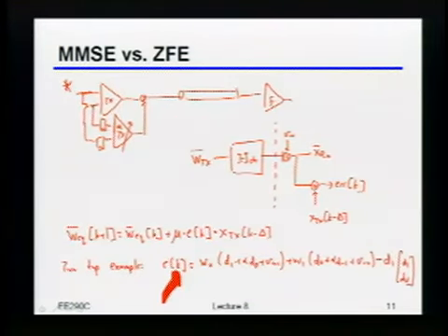That's really the problem. So assume if you have an analog transmit, you have some analog noise, then you are basically doing MMSE just for that. Yeah, okay, so you're right that if the noise was all on the transmit side, then you are doing an MMSE for whatever noise was... Oh, no, actually, I'm sorry. That's not actually true. You were saying that if I had an analog transmitter and there was analog noise on the transmitter, you'd be knocking that off. Unfortunately, even that's not true, because my reference doesn't know anything about the noise on the transmitter. The only way I get that reference is by making decisions on the receiver. And if those decisions have the value of that noise, then I'm making errors to begin with. You see what I mean?